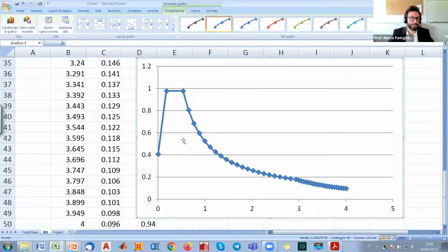This helps us to notice that the tool for the Italian building code provided the response spectrum with just 3 initial points, and with the second and the third, you have already defined the whole plateau. Then there is a mesh of points for the remaining 2 branches, where we have 1/T and 1/T squared as the proportional factors with respect to periods.